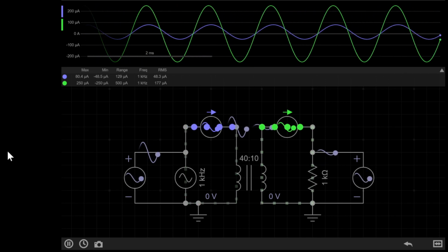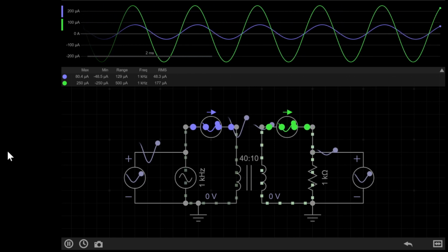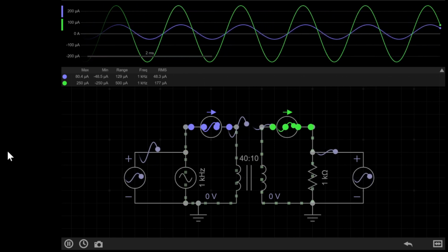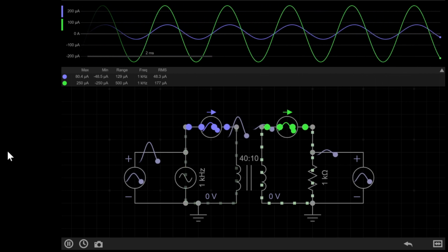However, if your circuit is isolated with a transformer, then there is no ground connection, so you will not get a shock. Please note though that if you touch both ends of a mains isolated secondary coil, you will still get electrocuted, so perhaps best not to touch live wires either way.